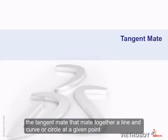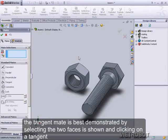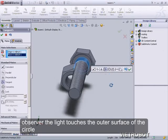The tangent mate will mate together a line and a curve or a circle at a given point. The tangent mate is best demonstrated by selecting the 2 faces as shown and clicking on Tangent. Observe that the line touches the outer surface of the circle.